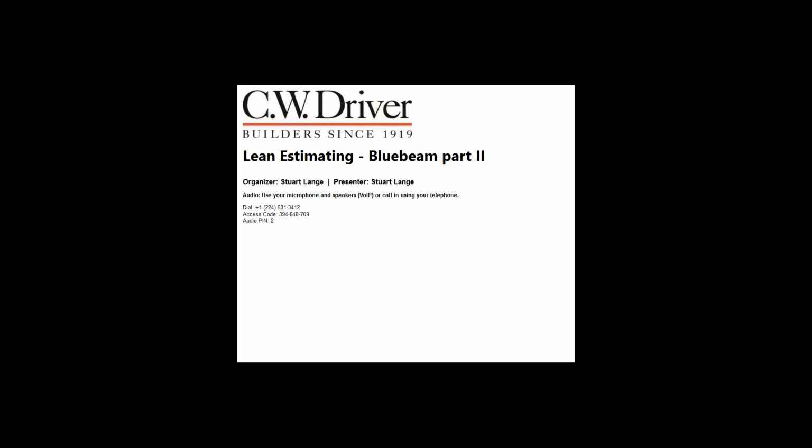So I'm over here, Stuart, and I click on what now? So link and then new. So even if they're extracted, you have a link. Yeah. So it's all relative to where it is in the file. So if you have a folder called plans and then a folder called architectural, structural, and so on, and files within all those, you can say batch link. And so instead of, when you click on A106 in the title sheet, jumping to that place in the same PDF, it'll jump and open that other file wherever it is in the folder structure.